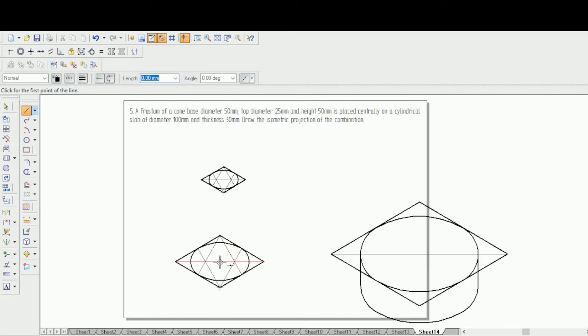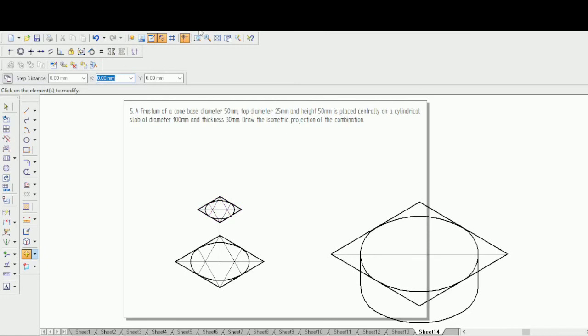So from this midpoint, when you are placing the mouse cursor exactly on this midpoint line, at exactly midpoint, you get this symbol indication that it indicates that this is the midpoint. So from there, draw a normal line. Let that normal line's height be 50. Enter. And now this one has to be moved over here. So just select this, pick exactly at its midpoint and place it over here.